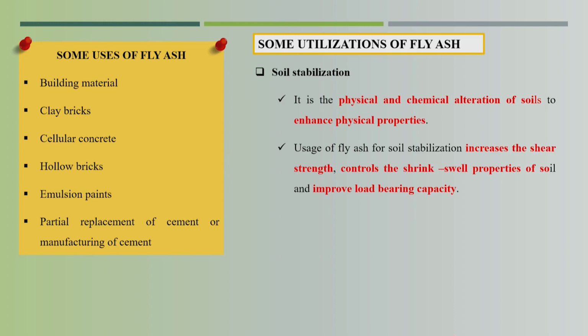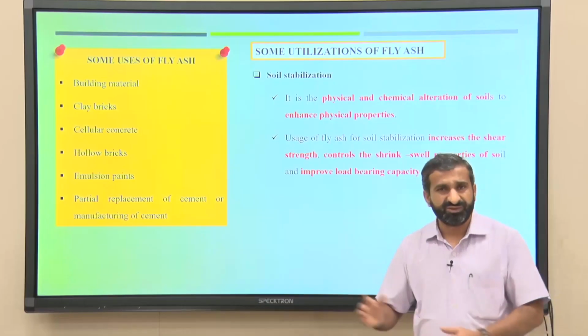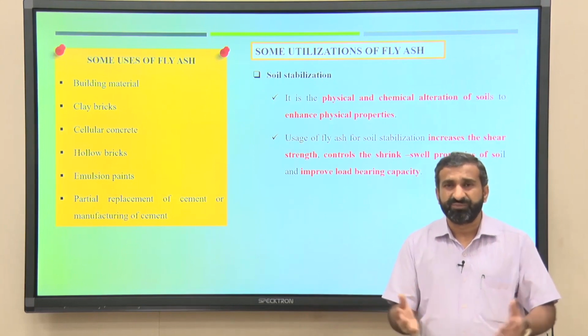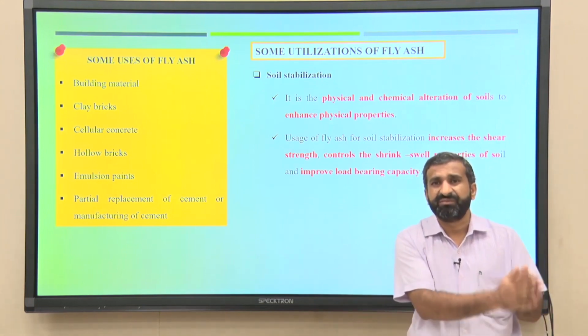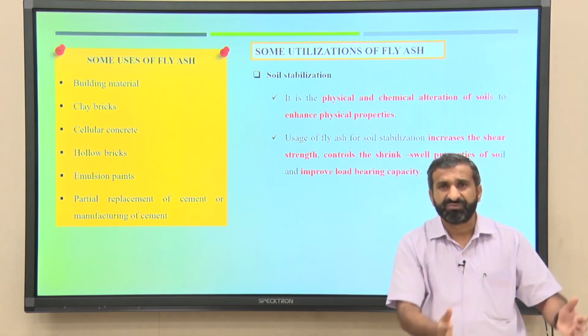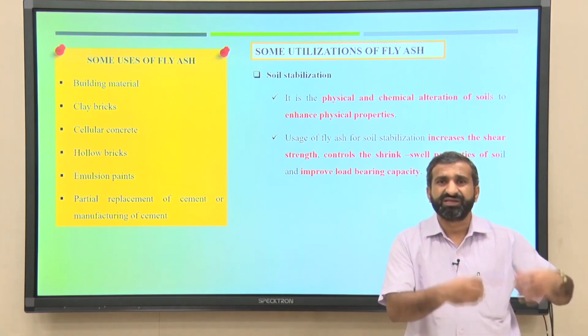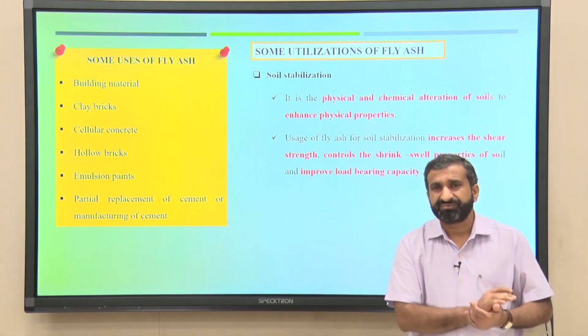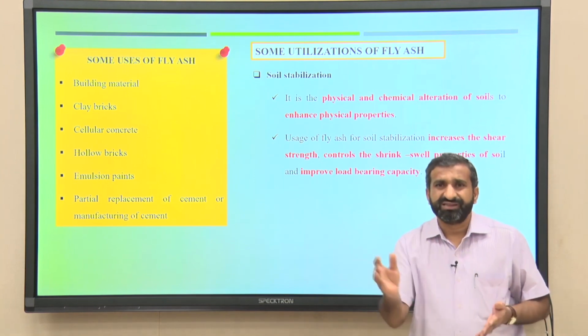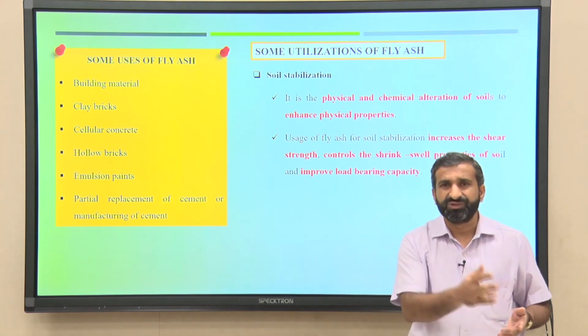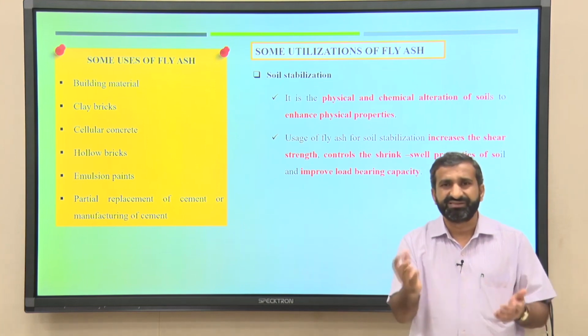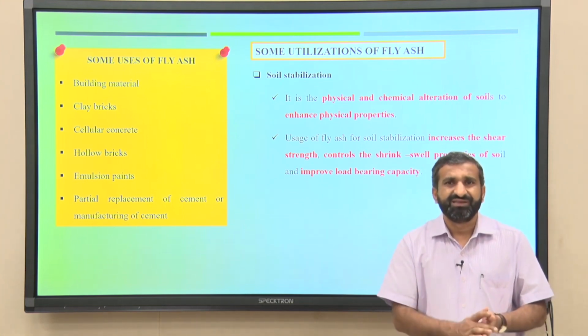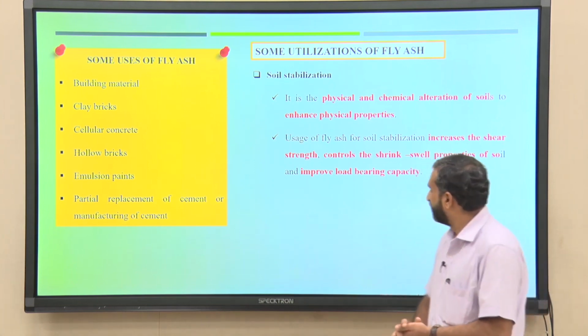So, it is also possible, and suppose somewhere some particular kind of embankment formation is required, with a large amount of soil, this bottom ash could be utilized to replace maybe 10%, 20%, depending upon the compressive strength or what exactly the strength of that particular embankment is required to be. But again, the same point I am saying, do the leaching experiments, and if it is under the standard, we can always use it for such purposes.